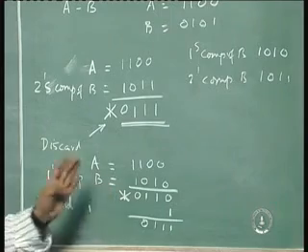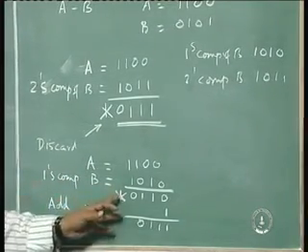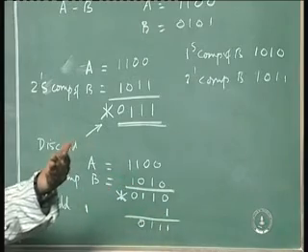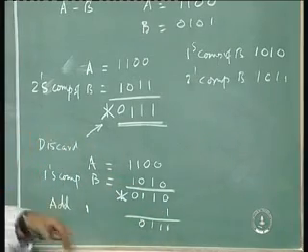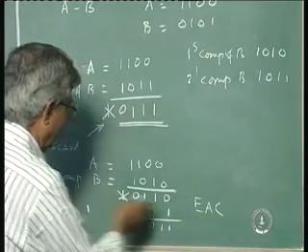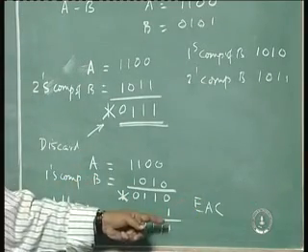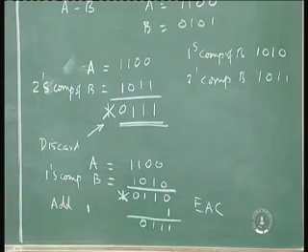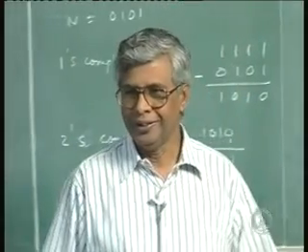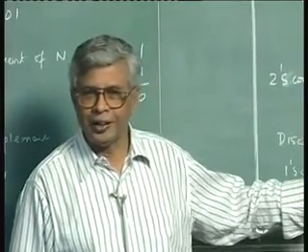Or you can say, sort of, it's not logical. This one is brought here and added, they say. It's called end around carry. You will see in the book, it's called EAC. You bring the carry around and add it here. It doesn't make sense. You have to add 1 to 2's complement number. It is not magic or something we are showing. So it is a logic.